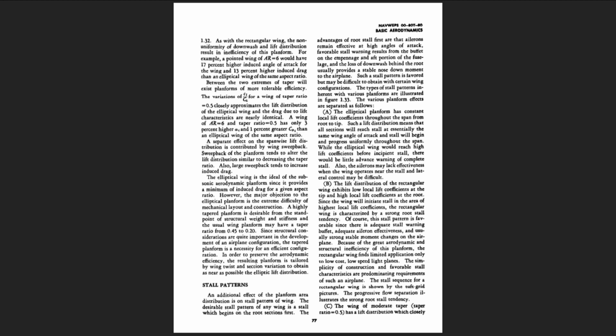In addition, the airfoil section may be varied throughout the span such that sections with greater thickness and camber are located in the areas of highest local lift coefficients. The higher c_l max of such sections can then develop the higher local c_l's and be less likely to stall. The addition of leading edge slots or slats toward the tip increase the local c_l max and stall angle of attack and are useful in allaying tip stall and loss of aileron effectiveness.